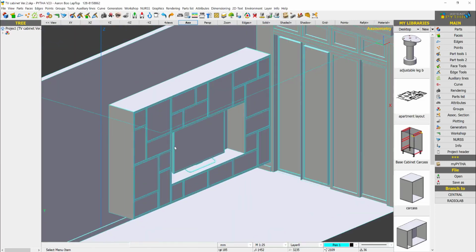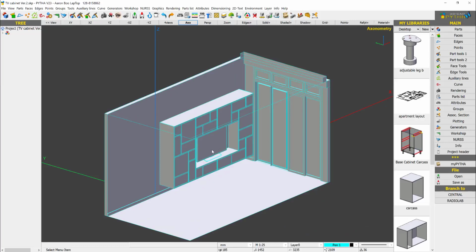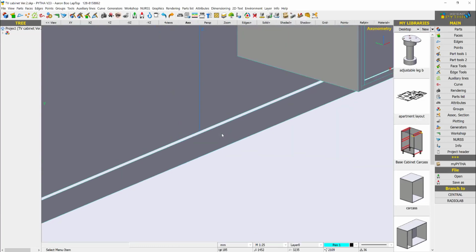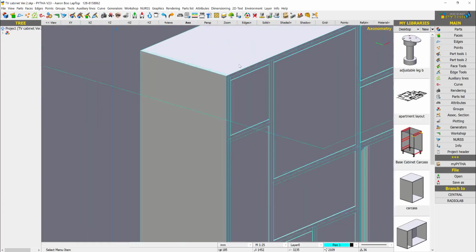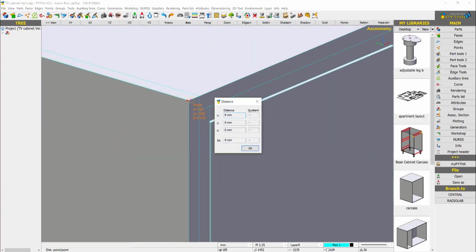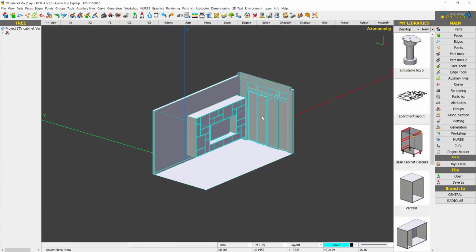What happens is SketchUp exports it in inches. So what you need to do, simply at the bottom, go to inch and say 1 mm is 1 inch. So nothing should change. And now go back to mm, but this time choose 1 inch to 25.4 mm. So once you have done that, if I were to press Ctrl T, you see that the measurement is 15, which is what we want.